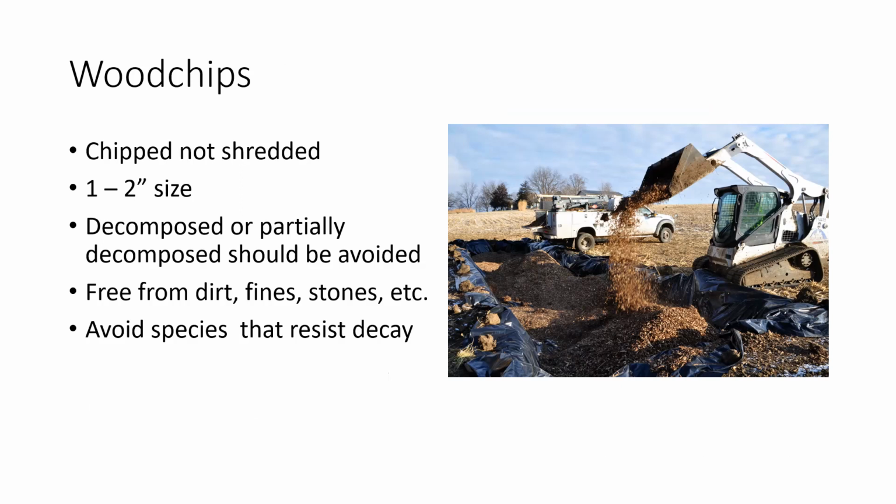Next, the wood chips for the bioreactor are really what make the magic happen. As I mentioned earlier, they provide the carbon source for microbes to utilize. We saturate those wood chips, and that takes the oxygen level down low. So the microbes down there need to find something besides oxygen to breathe, to metabolize the carbon in the wood chips. They go to the next easiest thing, and that's nitrate in the system. That's how they convert the nitrate to N2 gas: that saturated condition.